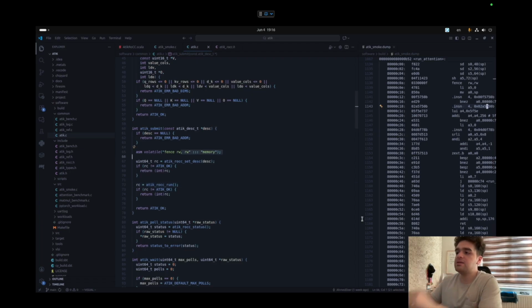And this is used for the sake of counting the cycles in the right way. We put a fence. This fence tells the Rocket Chip to not ever pass this instruction until it is finished. Because we are calculating how many cycles this instruction consumes from the chip itself, we need to put this fence so it doesn't pass it and we get wrong cycle counting.